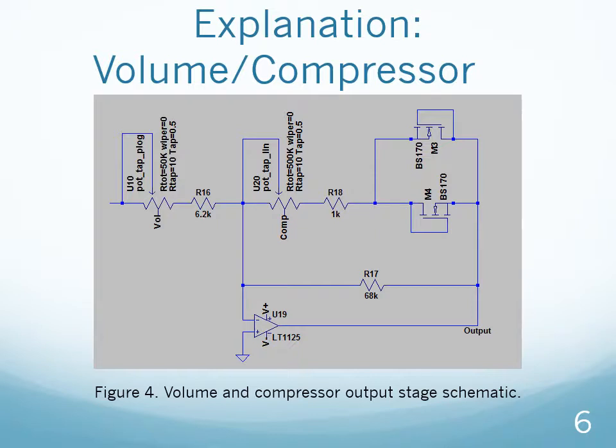They have different characteristics, so they sound different. In this case, I chose the MOSFET for the compressor and the germanium diodes for the clipping, because germanium has a softer knee. So if it's clipping, you would expect to see a very smooth curve, rather than one that flattens off harshly, like with an LED or something.